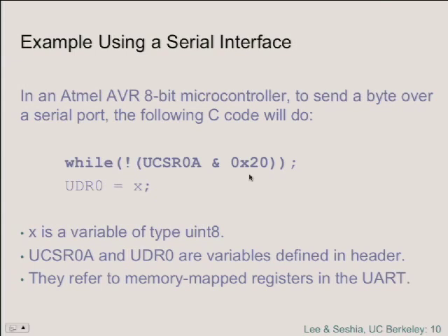So this while loop, which is empty, by the way, there's no instruction there, will simply keep executing until there's a byte for me. This is the polling scheme. So this C program just executes forever until that one bit of that memory mapped register goes to 1. At that point, we assume there's a byte for us, and so we read that byte. Oh, sorry, this is doing a write.